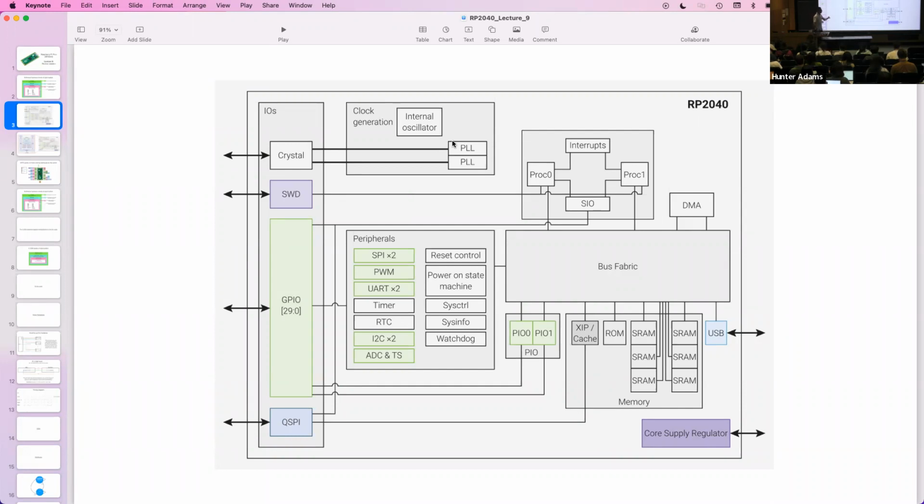There can be a funny consequence of this, incidentally. If you time your interrupt service routines, which is to say you time how long it takes, when the condition for an interrupt is satisfied, how many cycles does it take for you to get into that interrupt service routine? And it's going to take some non-zero number of cycles because the system has to store its state so that when it comes back out of the interrupt service routine, it can resume what it was doing.